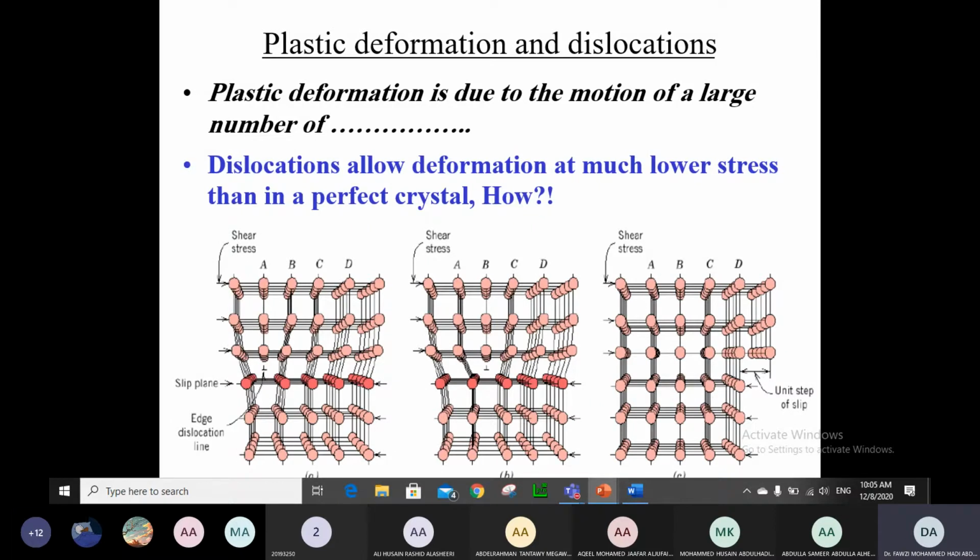When the dislocation is restricted from moving, you hold the dislocation and resist its movement, you make it harder for the slip to happen, and plastic deformation will not occur easily. That's why you have a higher strength requirement for plastic deformation to occur. So ductility will reduce and the strength of the material will increase. So this is what we did before.